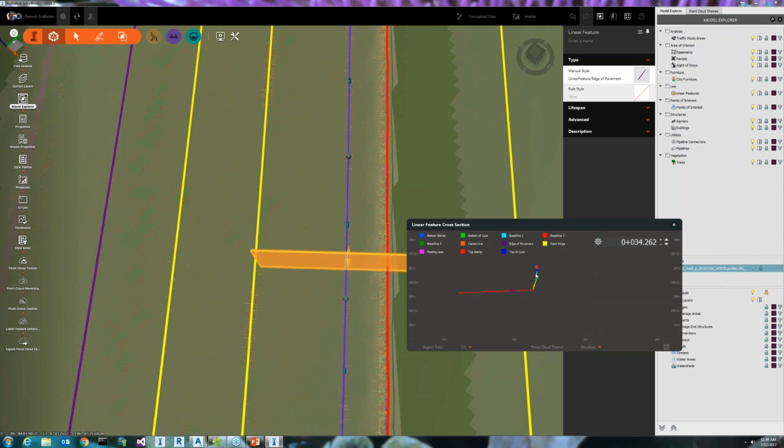Very easy. As a matter of fact, editing the vertex is very easy in cross-section. You can just click and drag it. Let me introduce the cross-section view first. There's a zoom-in option, or the exaggeration. We call it the aspect ratio here. You can go to much higher aspect ratios. It's very useful for the crown of the road or the edge of pavement, or a small embankment between the asphalt and the sand. You can even extract those things here. And there's a settings option that lets you control how much of a jump to make. For example here, I just put in 20 meters. Obviously, in a practical case you won't extract 20-meter spacing lines, but just for demonstration purposes I put in 20 meters. How much thickness you want, all those things you can control. As a user, you are definitely in the driving position, and you can choose how far. I'll show you how to traverse to the next one.